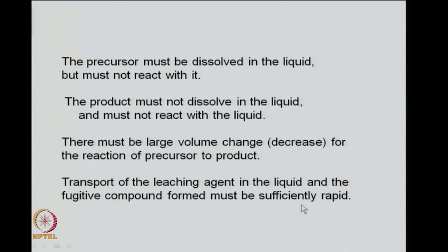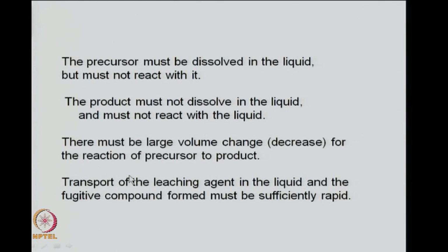That removal is important. So, these are some 4 criteria which are very carefully chosen while planning a typical spray pyrolysis process. You weigh in the factor of which precursor you want to choose, what kind of substrate you will use. All that has to be taken into account to plan for a proper spray pyrolysis process, such that you have good homogeneous particles of submicron size.